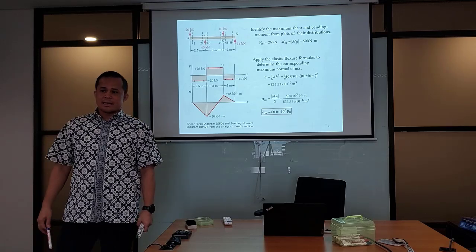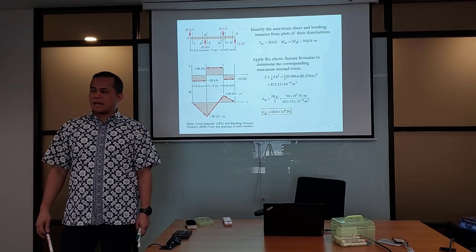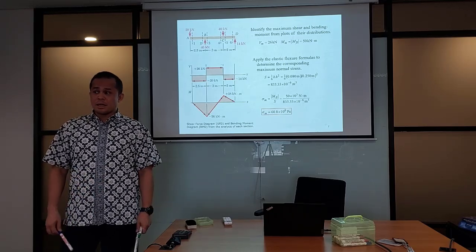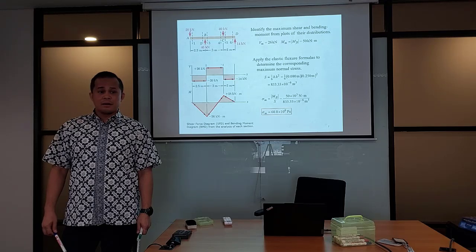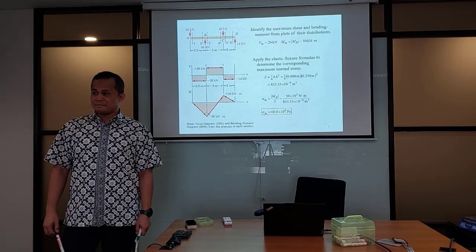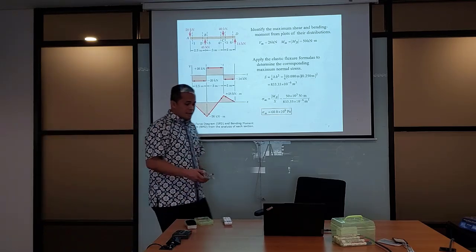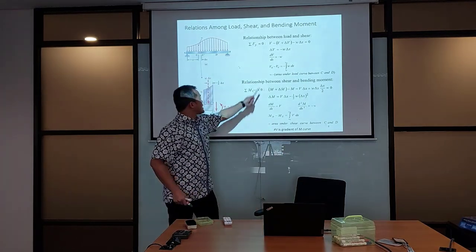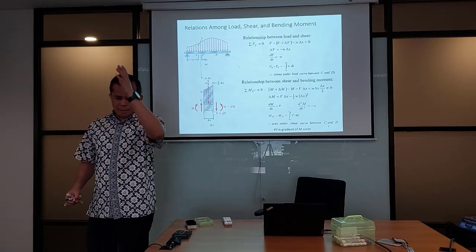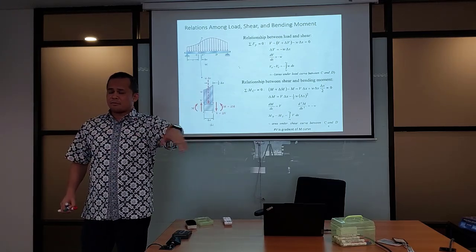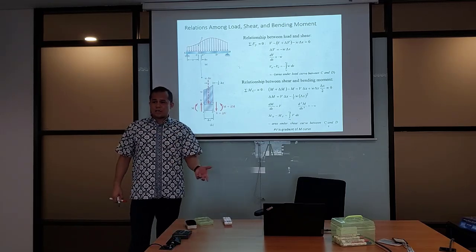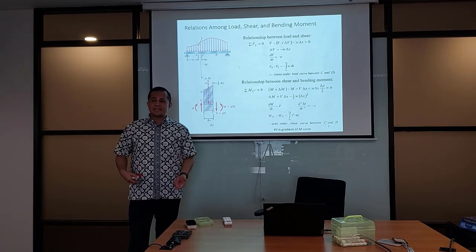If you integrate something from nothing, what will appear? Constant. So when you have a concentrated load, you want to know the shear force generated by it. It is a constant. As I told you, integration: a concentrated load has no function. It's just applied, and after this nothing. So meaning that from that point going onward, no applied load. Because no applied load, if you integrate, what you will get is a constant.